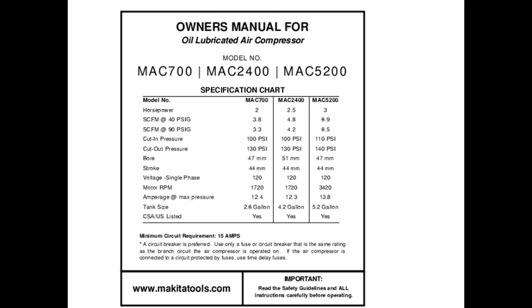So what would you operate your air tools at? Well, not 90 because it's going to cut in at 100. So on this one, you were going to, well, you're right. I'm sorry. 90, this would operate a 90 PSI tool, right? So what you want your tools that you get, you would want them to operate below the minimum pressure, right? Understand that.